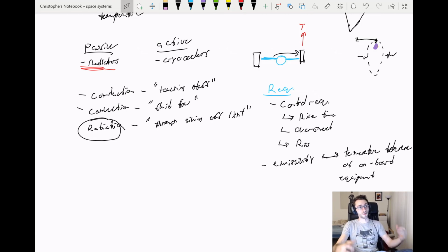And also, while you're in the view of the sun, it's radiating its energy onto you, which you are absorbing not only in your solar panels if you have them, which is being converted into electrical energy, but also on the satellite's surface itself, which is then conducting down to all your electrical components. So you want to make sure that the sun's radiation isn't going to provide a problem and exceed the tolerances that you set for temperature for all your onboard systems.